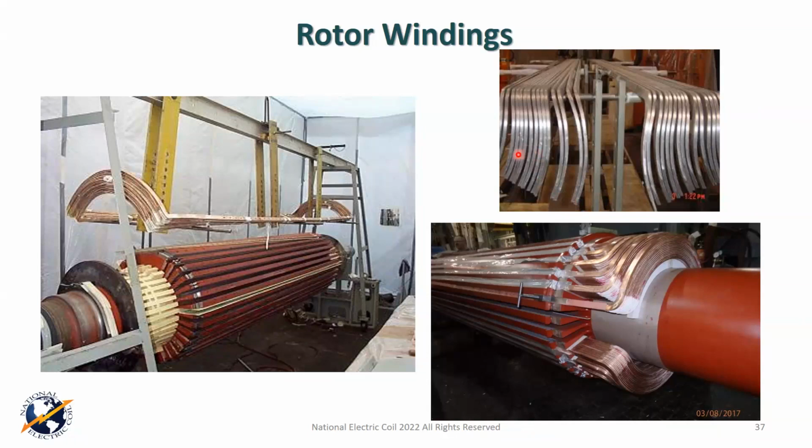Now, I probably won't have a ton of time to talk about cyclic operation today, but one of the big problems we face in our industry is rotors that are cyclically operated. The rotor is the component that's most affected by the cycling. One of the biggest problems was one of the huge fleets out there that had what I would call a fabricated coil with a square corner design with a miter and a fillet, applied on the 786s and some others that GE had.